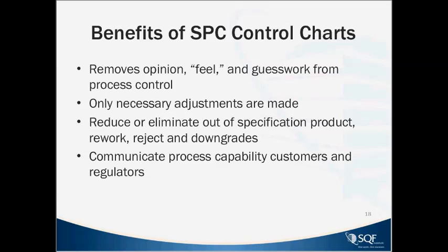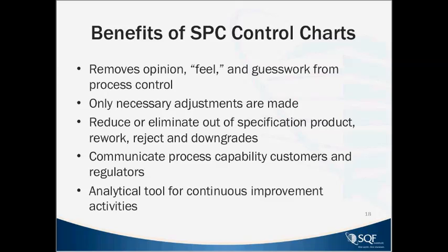That's one form of communication, but it could be very powerful if you could even submit a process capability study to your customer that would show that everything that you're making is 100% within spec. That's the power of that tool that you can now use with your customer in communicating those particular parameters to them.